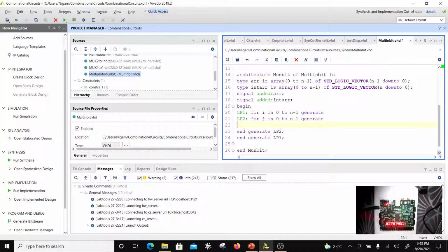And I'll tell you why high level synthesis has been developed. The high level synthesis or SystemC or any other form of high level synthesis exists because people are coming from computer backgrounds, right? So they are used to saying counter is equal to count plus 1. They are not used to using a T flip-flop to do a counter. Similarly, if I say multiplier, then all the software guys are used to A into B. But you know that in hardware it doesn't go like that, right? Of course you can synthesize with Q assigned A into B, but this is a high level construct. This is a behavior.